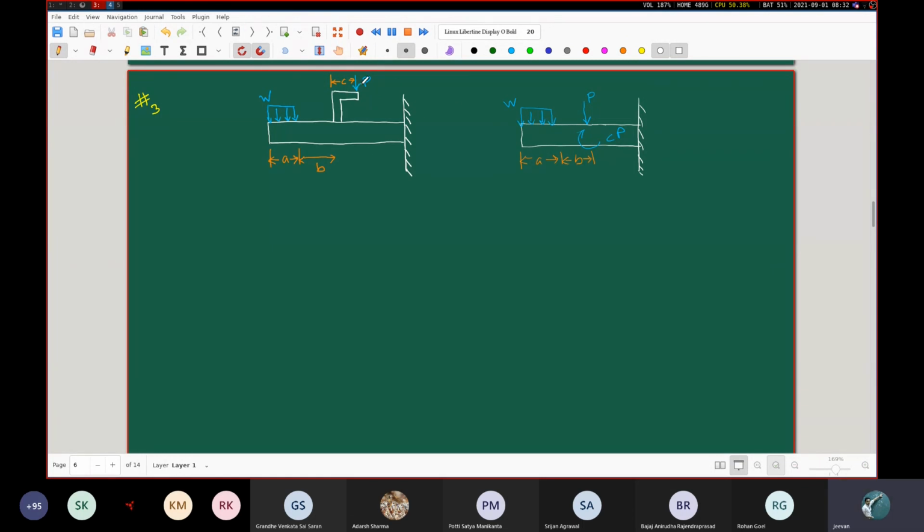However, when we are translating this force to this part, we are separating the beam and this little inverted L-shaped part, and considering the influence of this L-shaped part on the beam. Effectively what you are doing here is separating out that L-shaped part and considering the entire influence it was having on this beam.